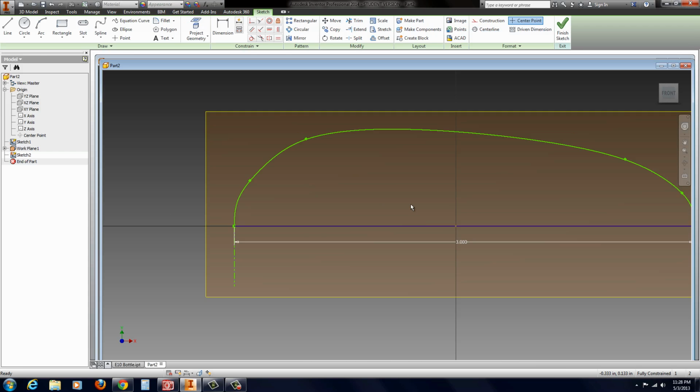And now we draw the top of the bottle. So again, using the same technique as before, and this is going to be a little offset. We're going to click and drag off a line, escape, and then just make sure you align those with a coincident relationship. We'll dimension it. And we'll make it 0.5.